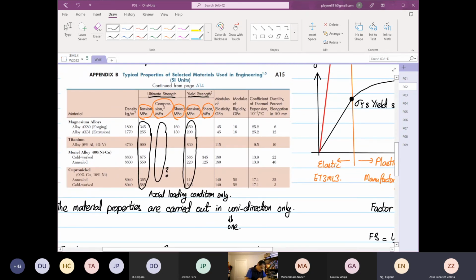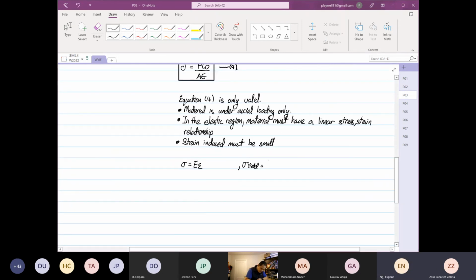Let's look at, I did not copy the standard material. Anyway, let's look at titanium. Titanium is a strong material. Okay, we're not working on titanium, we are working on steel. So steel, I can give you approximate. Okay, steel is about 650 megapascal. Okay, so steel at 650 megapascal is usually in a range of AISI 1045. Okay, the Young's modulus will be about 200 gigapascal, for example.